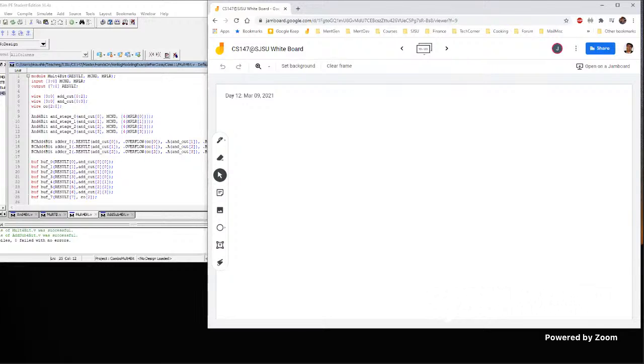4-bit AND with one part the multiplicand, which is all 4 bits, and another part is the 4-bit replication of the multiplier, the MPLR LSB, the 0th bit. So this is almost like taking 1 bit and replicating it 4 times.